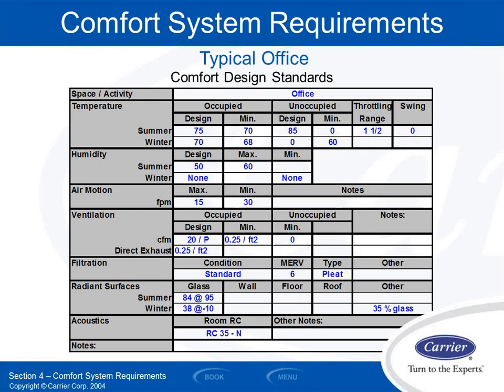For example, in a gas furnace, I might have a certain size heat exchanger, my flame is at a certain rate, and I got a certain efficiency. If I was to double the size of that heat exchanger, that extra surface area would give me more heat transfer and hence higher efficiency levels. Well, I'm not going to double the heat exchanger during operating time, right? I can't just randomly do that. But when I don't need full load, I could throttle the burner capacity back and give you less gas flow, which is kind of the same effect as having an oversized heat exchanger during those part load scenarios. So I'm able to be much more efficient than whatever the published data is for a piece of equipment when I operate it at part load.